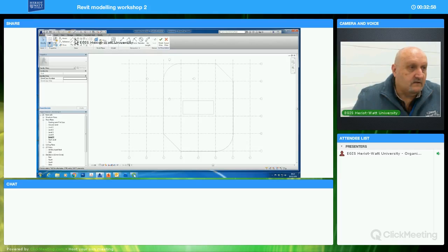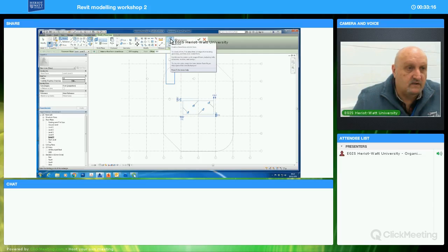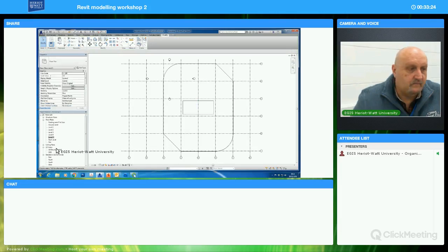And because it's rectangular, the rectangular tool just sits in there. And I'm simply going to, on this occasion, copy the shape of the shaft opening. The bit I would like to draw attention to is the bit that people forget, is create the solid form in here. So create the form. You'll get this form of cursor appear, and you can just finish that mass.